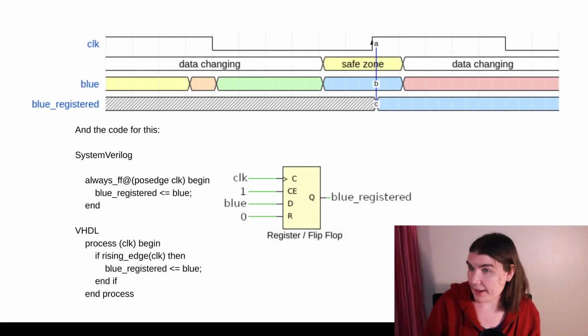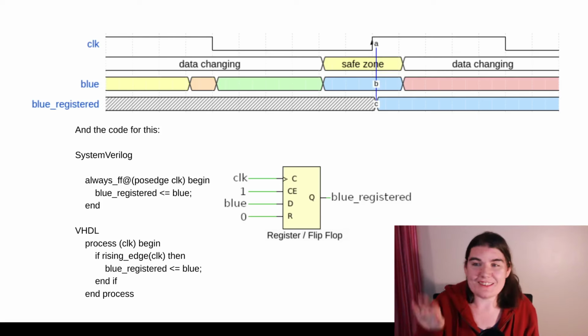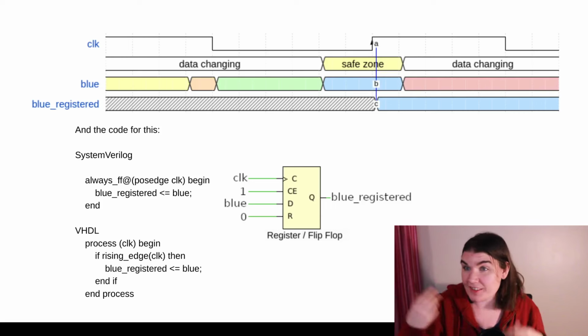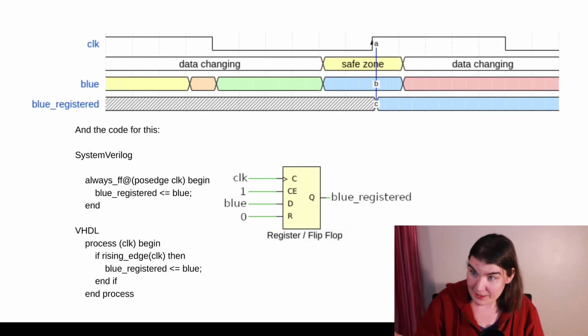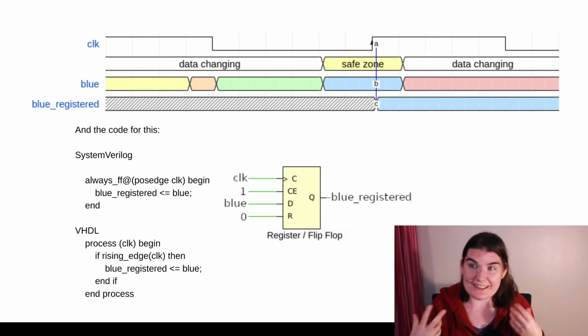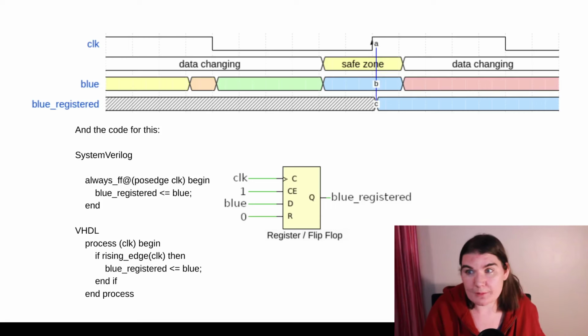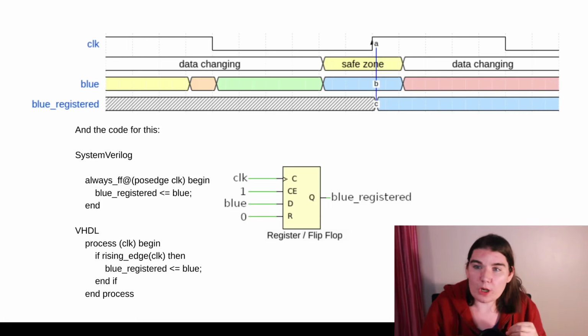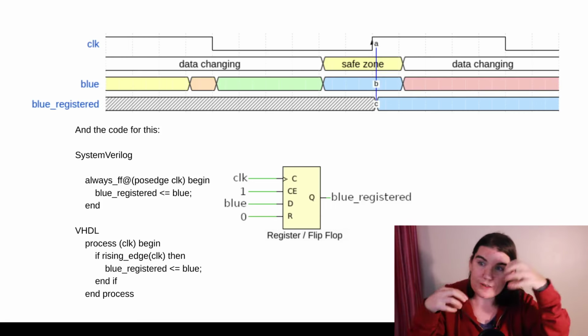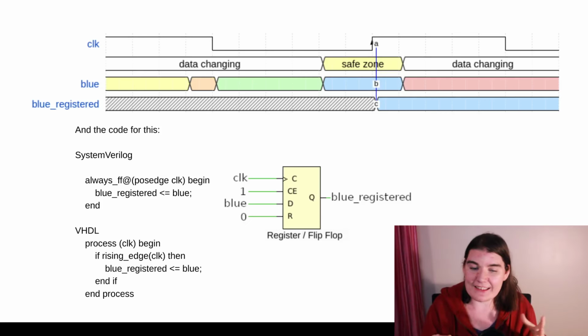They don't have a clock input. They just decide between signals, just like the code I wrote earlier. That was a mux, and that mux will be synthesized into a LUT, and it doesn't have a clock. And so this fundamental building block of the FPGA is like a little Lego block. The FPGA is a bunch of little Lego blocks that you build together, connect together.